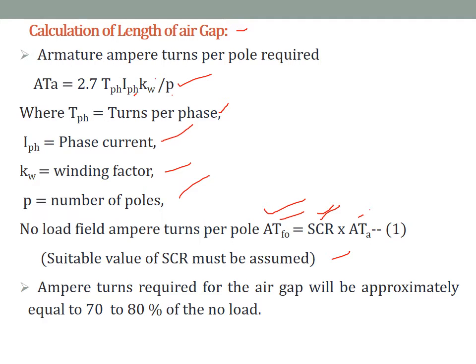And also the ampere turns required for the air gap, that is called ATG, will be approximately equal to 70 to 80% of the no load field ampere turns.